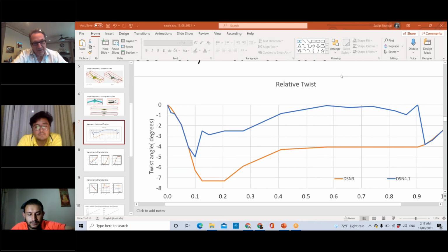Some people, so we've tested 2-position nose gear when we've done takeoff things, an extended nose gear for takeoff and retracted halfway for landing. Right now it's still at lift equals weight, so when you land, a little bit of a bounce and it pitches up and it goes up. But if you take that landing gear down a third even of that height, it'll stick the landing.